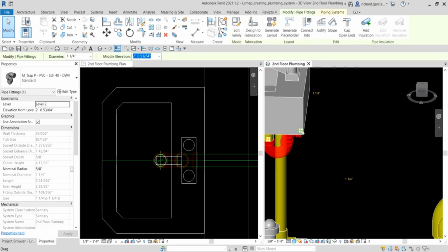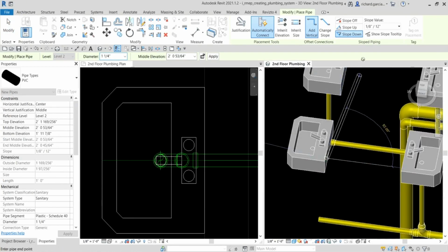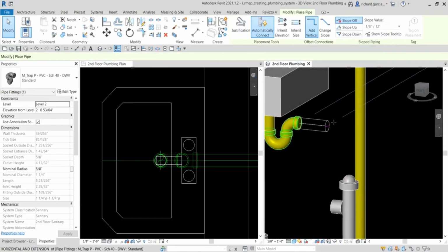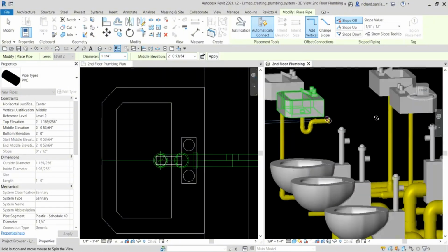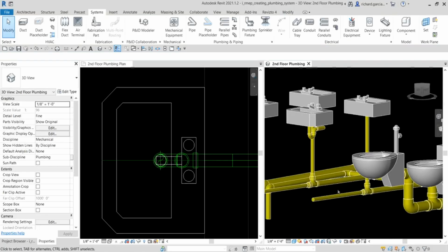So you click that, right click that, draw pipe, okay, and then pick slope off. So you pick that, right click, draw pipe. So let's pick 1 point. There you go. Okay. And then you can now connect that to your connection here. Okay. So you can use a line tool. You can move this. You can create a pipe going down and then connect it from there.